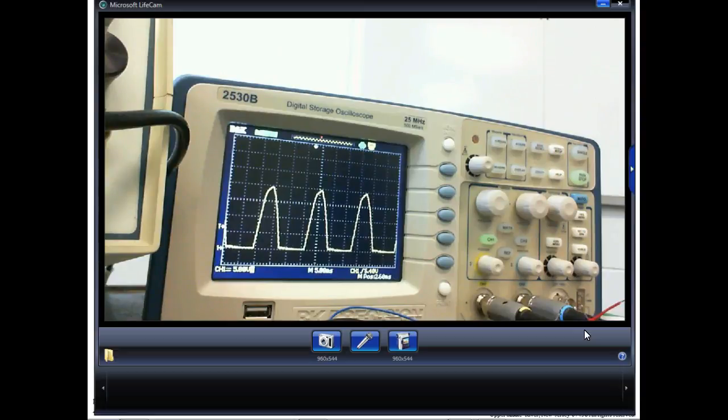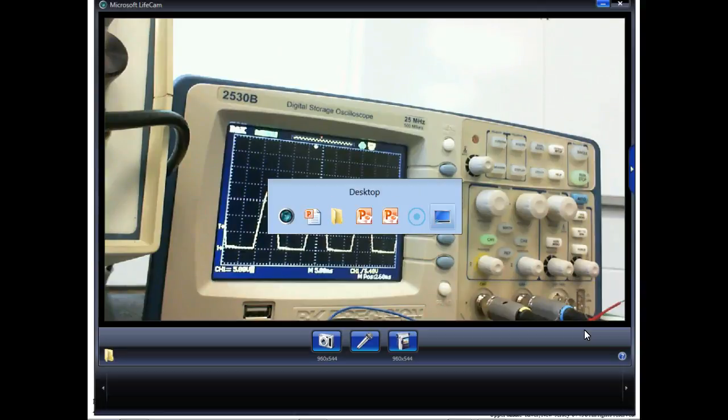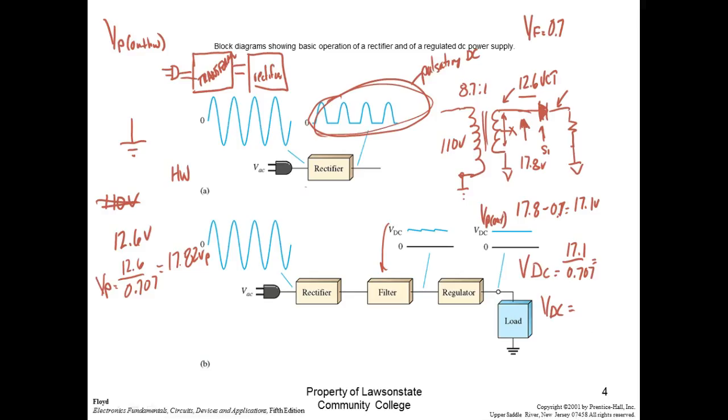If I double the voltage, now we're not talking about the source. You said, now wait a minute, you said power doesn't change, but that's the source, that's the transformer. We're talking about a load. I've got a resistor out there and I'm putting 5 volts on it. And I raise that voltage up to 10 volts, what happens to the power dissipated by the resistor? Well, we've got one resistor, so we're not changing the resistance. Somebody give me, how many people say it's going to double?